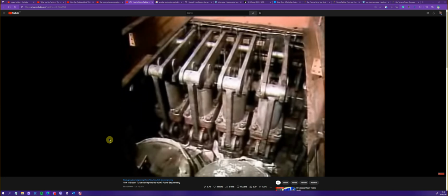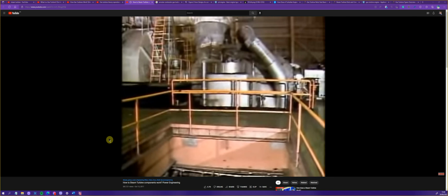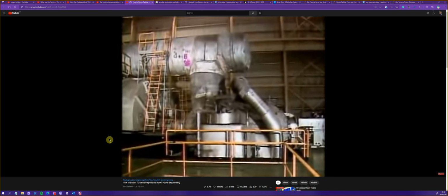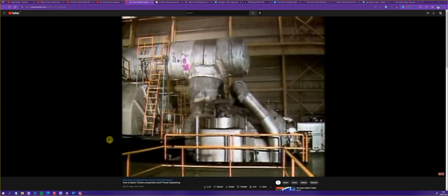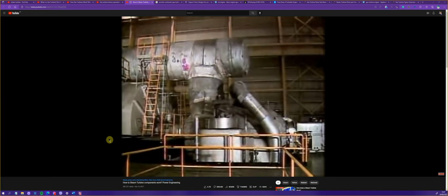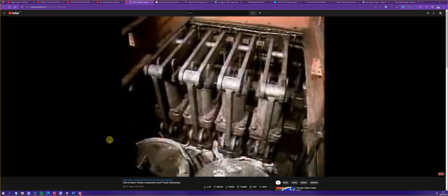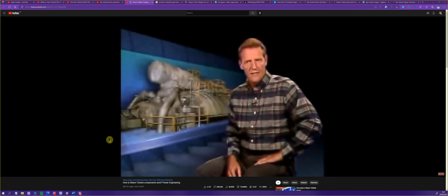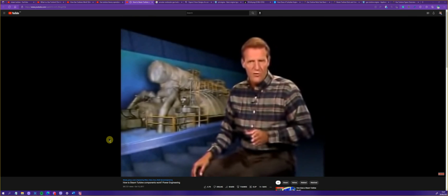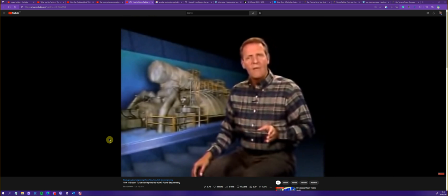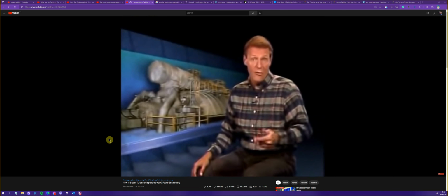As you know, turbine speed is regulated by the control valves. If turbine speed increases during normal operation, how do you think the control valves will respond? If turbine speed increases, the turbine control valves will compensate by closing. Under certain unusual conditions, the turbine may begin to overspeed. That is, the turbine may begin rotating at a rate higher than it was designed to handle.